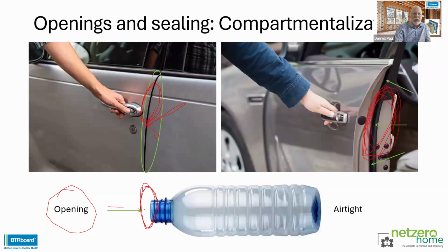As we try and push air into that, it creates a high pressure. And because the backside of this window is airtight, or the backside of this door that we're looking at is airtight, then it just creates a higher pressure inside here. Once that's full, no more air gets in. So think of rain coming down here and trying to get into that bottle. If it's already full of air, no air gets in, which means it can't transport any more moisture in there from rain. And if you look at it from the opposing side, it's the same thing.